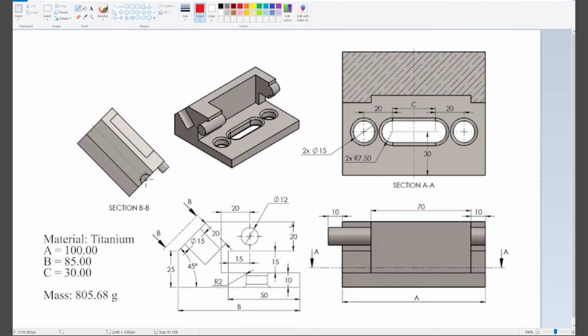Next up, we've got the views that they're using in this drawing, and this is actually very helpful for you to be able to make this part easier. You've got this section view, like Abe was talking about in the last part. This section view is this face here, normal to that face. We've cut off this top part, so you don't have to deal with that, right?